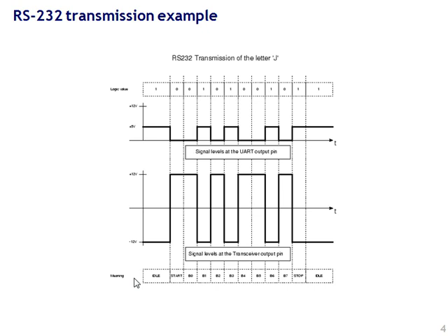8 data bits, no parity, 1 stop bit. The stop bit and the start bit are known as framing bits. You always want a start bit and a stop bit so that you can synchronize the data clock that's internal to the UART. The UART has its own clock, and that clock has to be synchronized with the transmit clock and the receive clock for the peripheral.